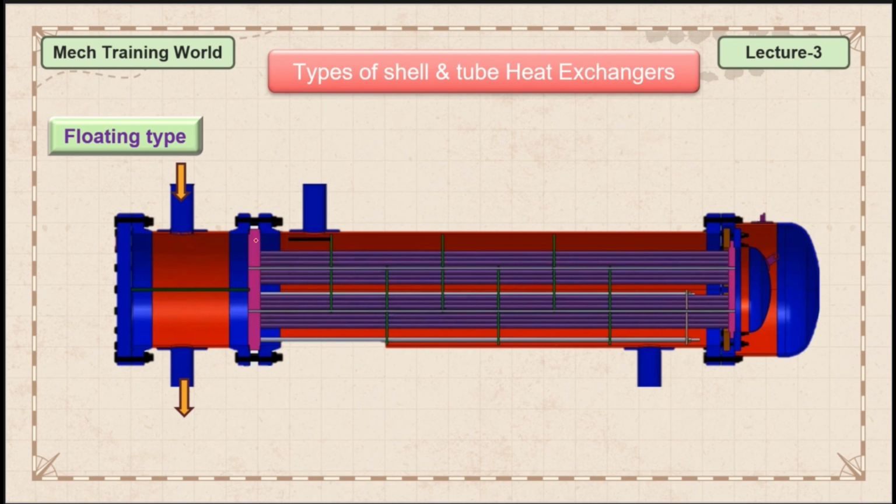One side of the tubes is fixed here, and the other side is not fixed to the tube sheet. Okay. So there is a provision for expansion or contraction here. So there is no thermal stress induced in this case.